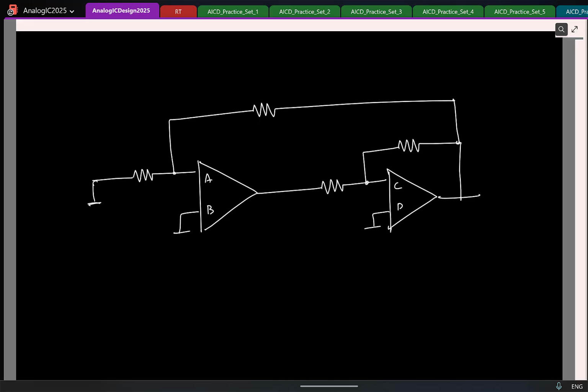And again, remember, our goal is to make sure both the op-amps, let us say this is op-amp 1, op-amp 2, both of them should be negative feedback finally, right? So how do you think we can go about finding what are the correct signs? We can? Yeah, you can, because there are only two possibilities for C, plus or minus. You can assume something. So what do you want me to assume? Let us say I'll assume plus, minus.